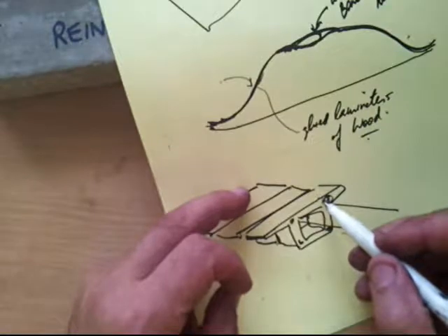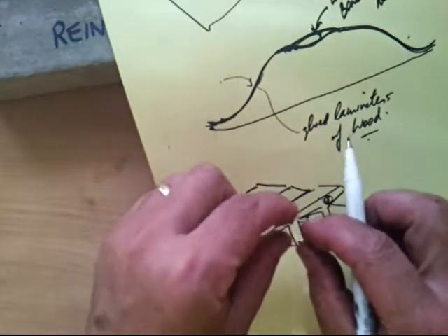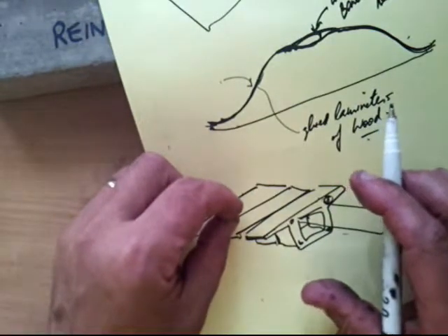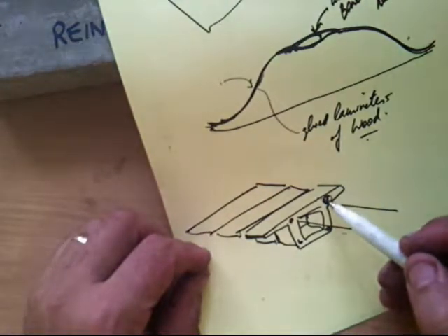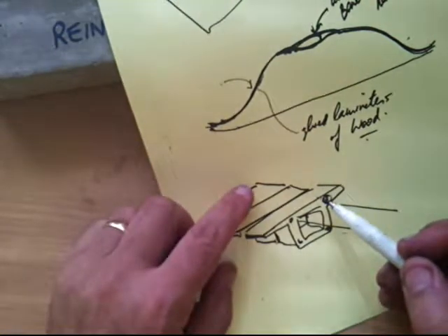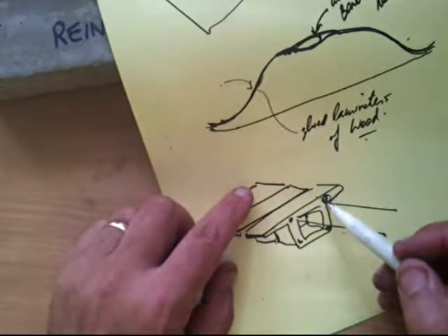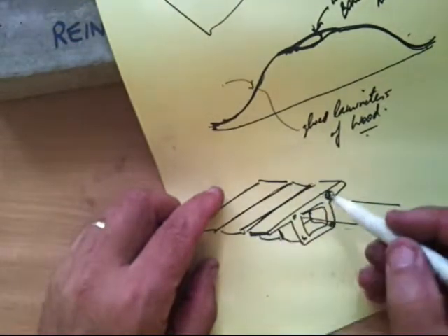And those sections then have been post-tensioned, so they've been tensioned after they've been cast, as opposed to pre-tensioned, where the tendons are pre-stressed and then the concrete is cast around the already stressed tendons. Here they're put in afterwards. And that's useful here because you can control the amount of pressure that you put afterwards.